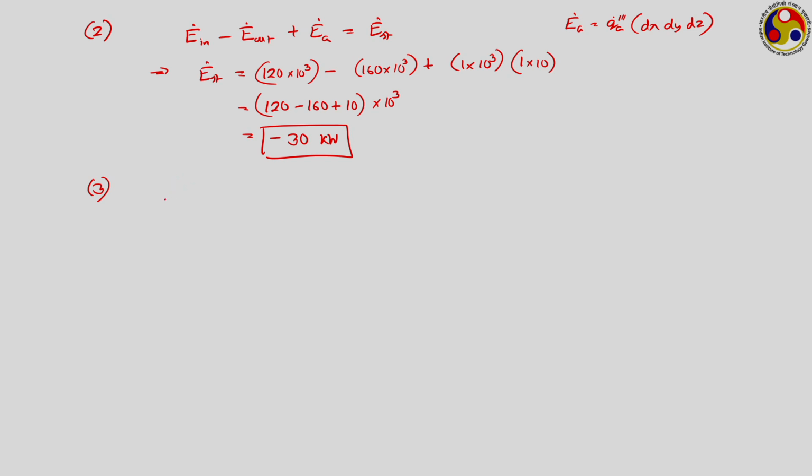So, we had k d2T dx2 plus q g dot triple prime. We are writing the heat diffusion equation, but it is the one dimensional version, assuming an isotropic material, that is with constant k. So, the k has come out and it is one dimension, only x is the direction. So, this should be equal to rho c into dou T dou t. I should stick to the partial derivative notation, because T in this case is varying both with time and x direction.